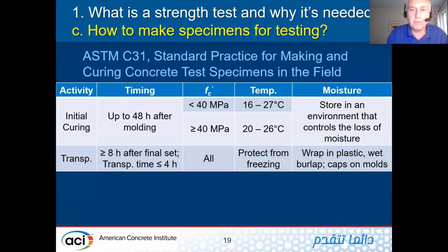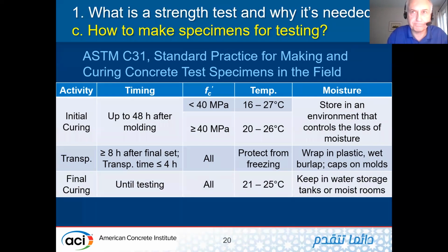There's no requirement regarding temperature except protection from freezing, which in case of Dubai and the Middle East doesn't really apply. So the temperature can exceed the 26, 27 degrees Celsius that was required for initial curing, but the moisture must be protected from evaporation.